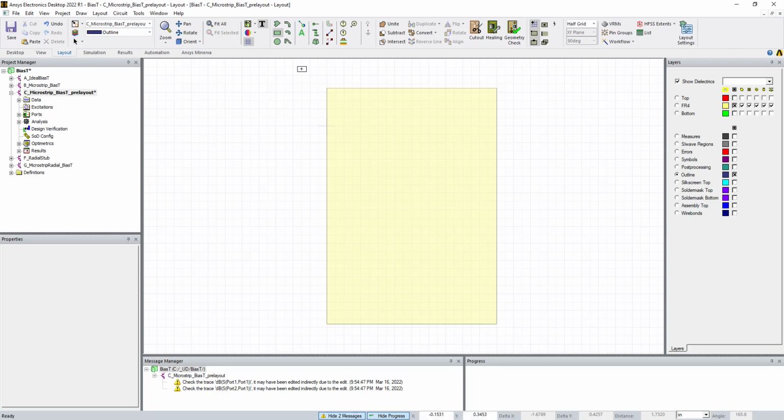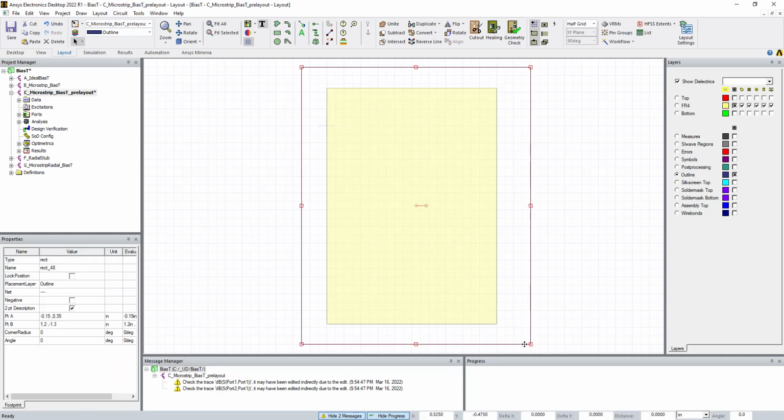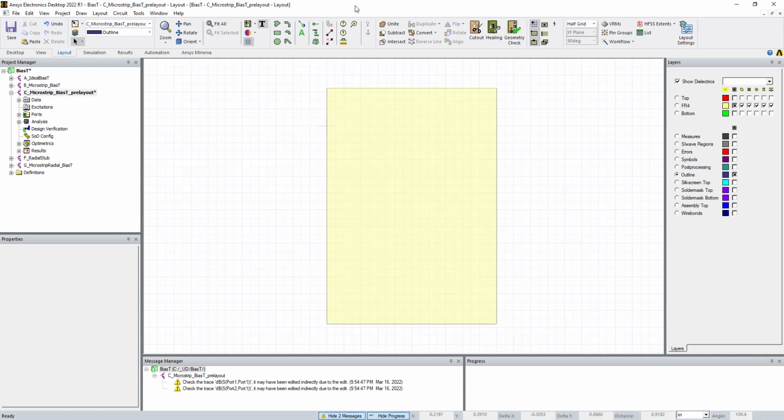So if you just drew a square and said, oh, I'm going to do the outline layer there, like that, it doesn't work. The printed circuit board shops, and I've tried this, will not recognize a closed zero width polygon as the outline layer. You need to do a zero width non-connected line. So the way you do that is you draw the line. I'm just going to connect here, connect there, connect there, connect there, connect there, right click and say finish.